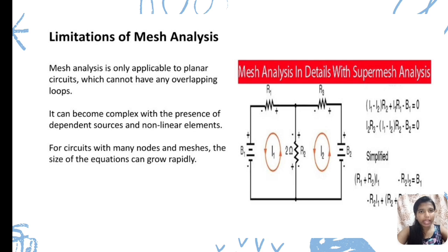Limitations of mesh analysis. Mesh analysis is only applicable to planar circuits, which cannot have any overlapping loops. It can become complex with the presence of dependent sources and nonlinear elements. For circuits with many nodes and meshes, the size of the equations can grow rapidly.